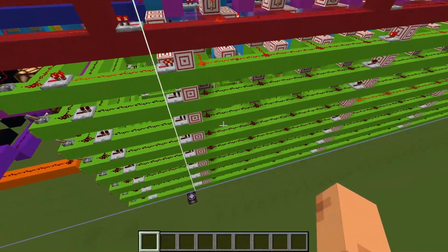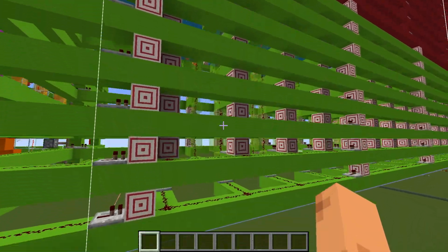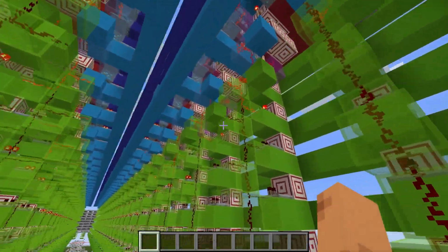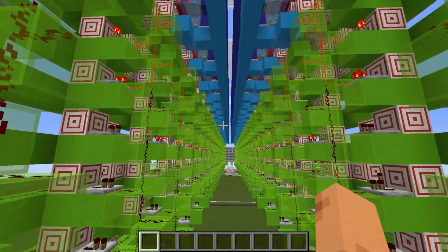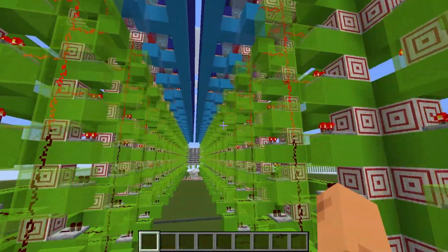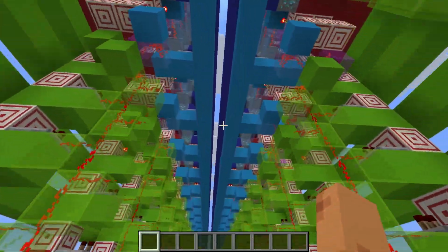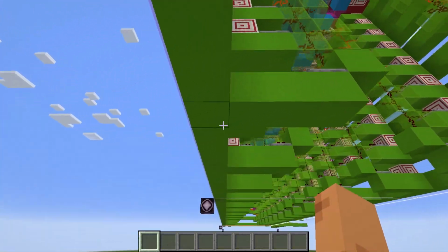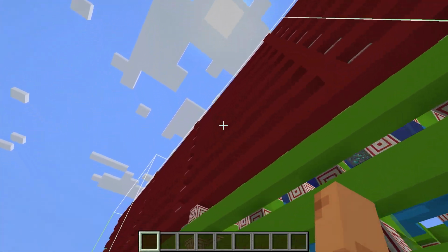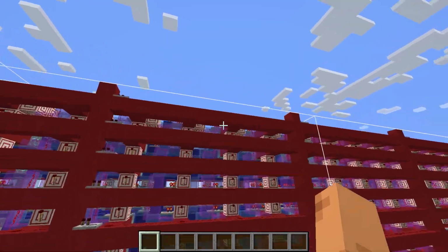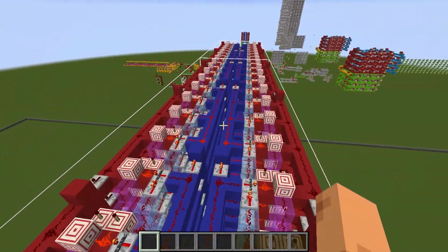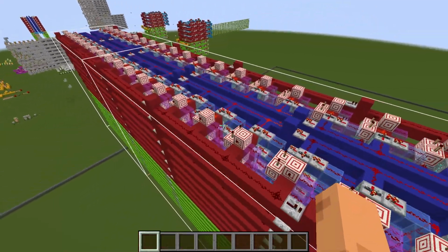That's down here with these green lines. And because we have to decode, this is effectively a decoder here, all this logic that figures out which cell we actually want to address is activated at a given time. And that's for writing to that memory and also reading from it.